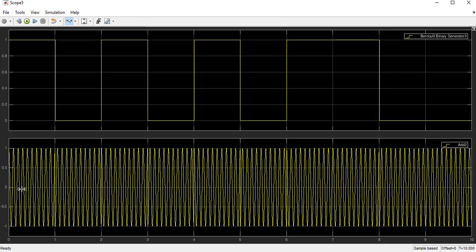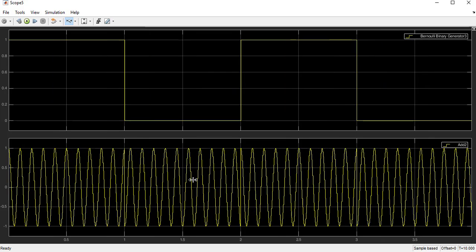So here you can see it's not very evident. Let me just zoom it a bit. Let me zoom it for four cycles. Okay, here you can see when my input was high, I am having a cos wave. You can see it's a cos wave because it's starting from 1. Here there is a transition from 1 to 0, and you will see a definite sharp change of the wave. The ending of this wave was here. You can see it's clearly here.